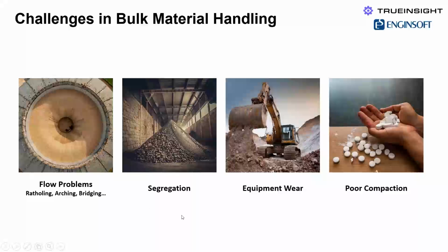The second challenge is that of segregation, where we have different size particles that are interacting with each other, and they may segregate into different portions of the volume. That will influence the behavior because it's no longer a homogeneous collection of particles.